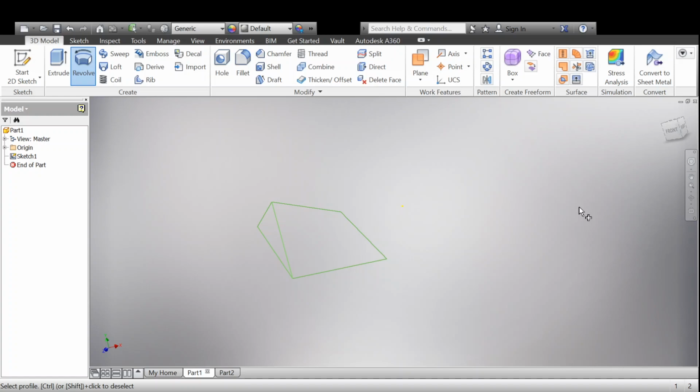We need an axis. Why do we need an axis? Use common sense. If we're using a revolve feature, why do we need an axis? It needs to revolve around something, literally. Whereas an extrusion is taking a sketch and making a 3D solid from it by literally drafting it or pulling it out of the screen into the Z dimension. It's kind of like what these do.